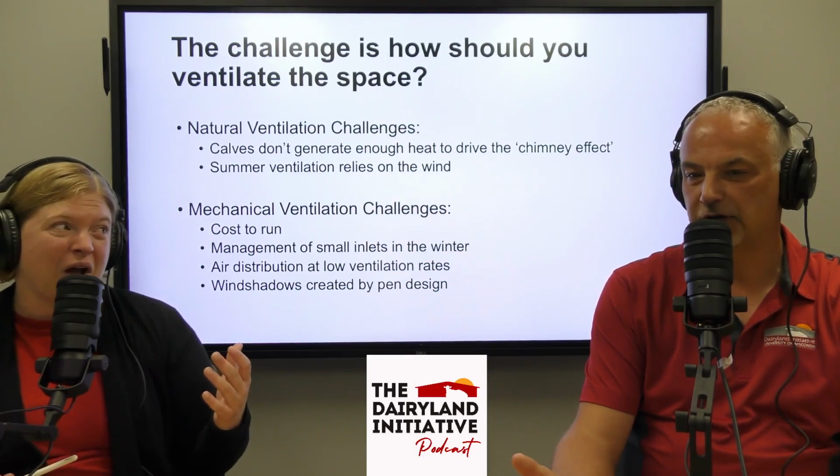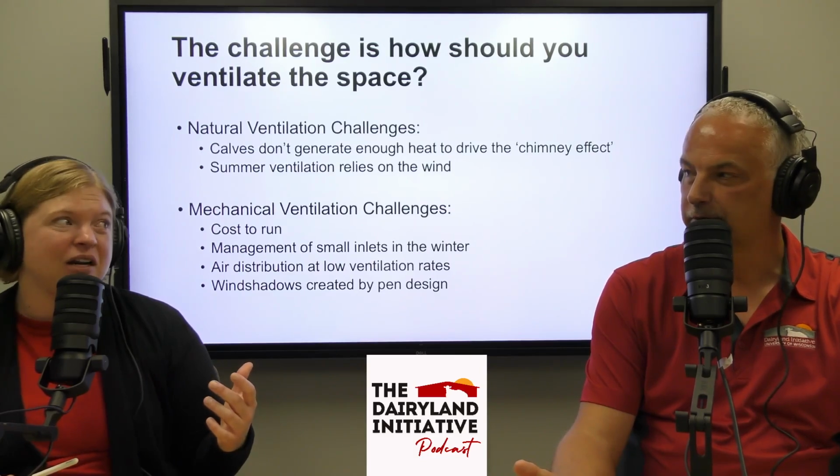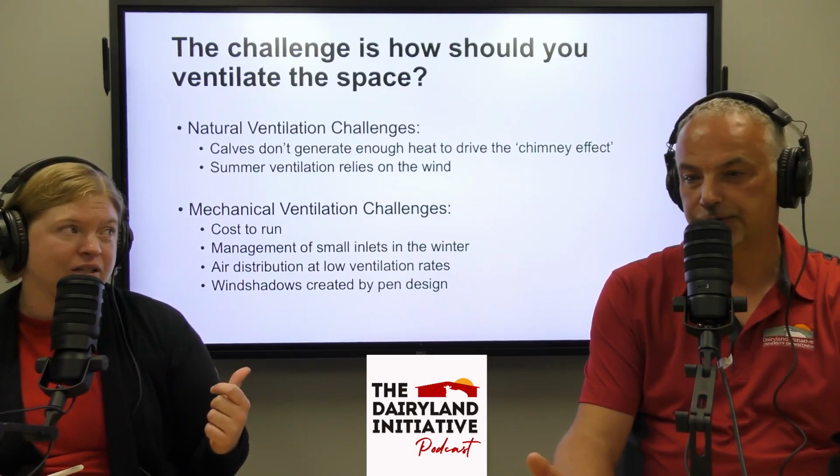There's a ridge opening in the middle of the ceiling, as fresh air is coming in through an open eave or open curtain. And then once we get to the summer months, it gets really hard because we're just relying on wind. And 4 air changes now isn't going to cut it in the summer. We need to up it to 40 air changes an hour. A tenfold increase. You're relying on the wind for that.